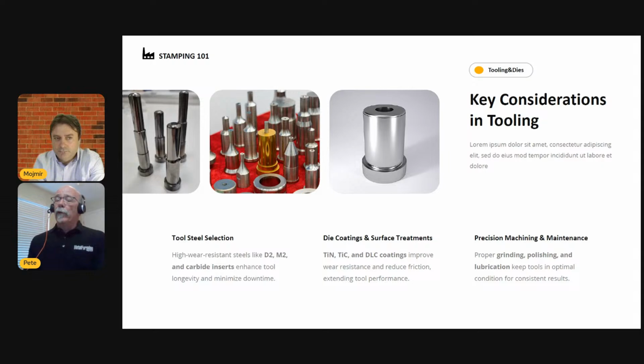And these high-speed steel grades are also available in powdered metallurgy. These would be the PM grade materials. And as we get into the PM grades, they are kind of like customizable materials. That's why there's a number of different grades. We can get some PM materials that have very high toughness, and we may sacrifice some wear resistance in order to get that toughness. And we're going to select these materials based on the forming failures or the die failures that we see in our tools.